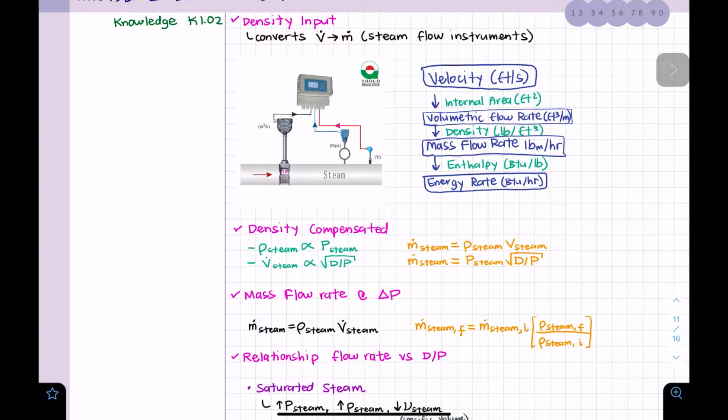They are single element instruments. I think theirs are called single, but anyway, there is like a multi-variable type of instrument where we have everything in here. It's just one instrument, and these are supposed to be better because we don't have too many holes where we can have some leakage, right? So that's gonna be better. We have less risk of having some orifices here and having some leakage there.